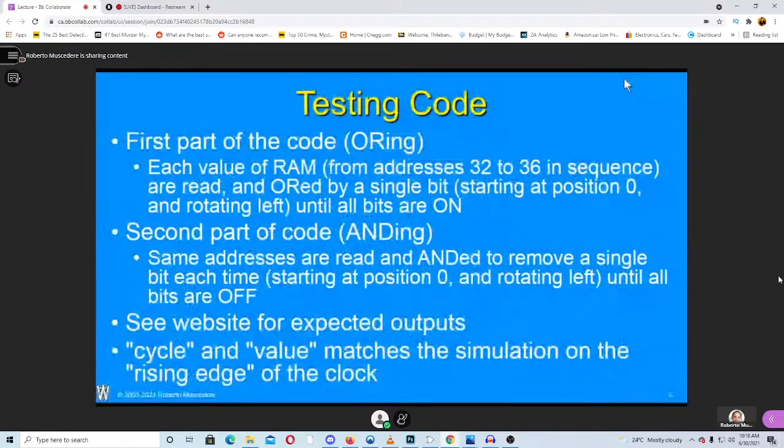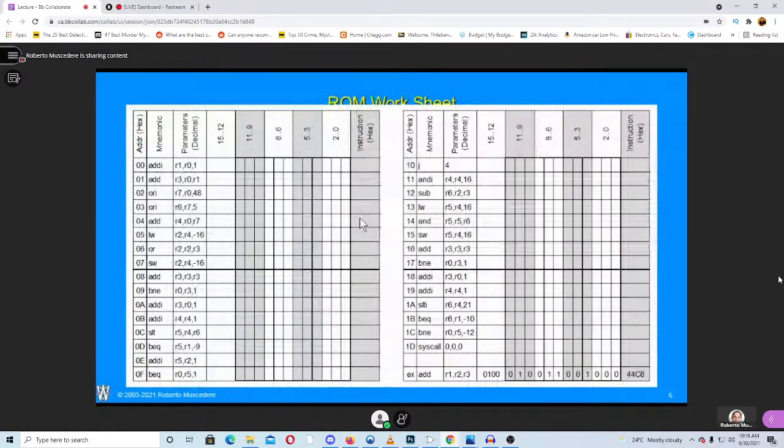Okay, I'll put that away. So as far as the actual ROM worksheet, I don't know why this got cut off, but sometimes it happens. Here it is. So you can see the code is longer. And because we've made it so these individual RD, RT, and RS are now 3 bits, you'll notice there's a thicker black line here going every 4 bits. So this is 16 bits here. The opcode is 4 bits, so I didn't break this up for you, but these are. So you can see how these 3-bit numbers overlap on the 4-bit boundaries.